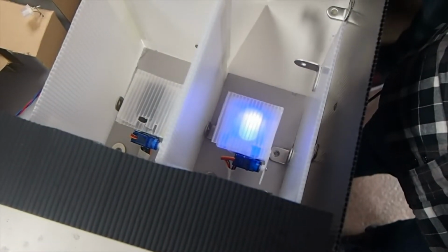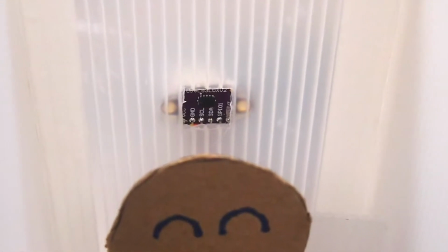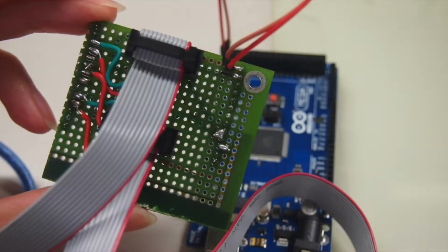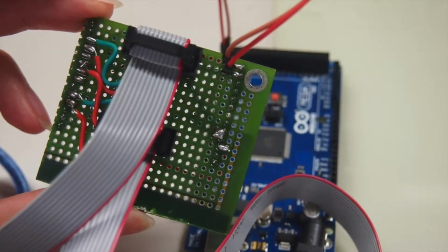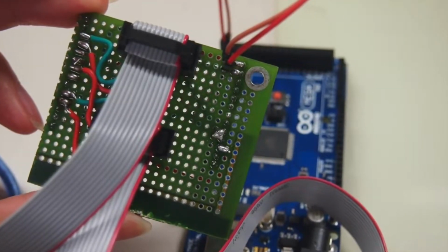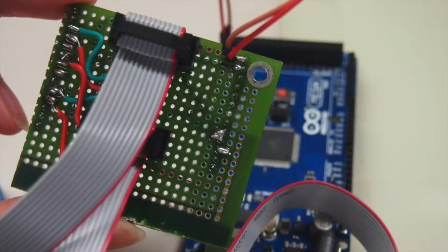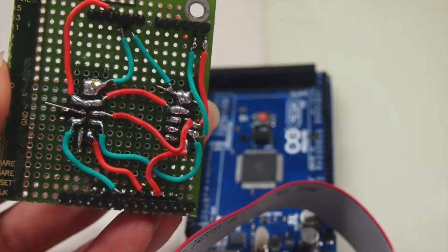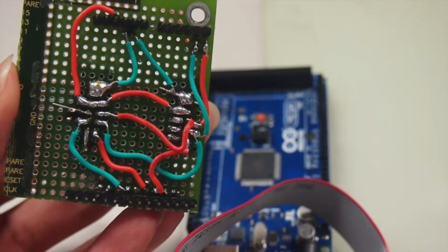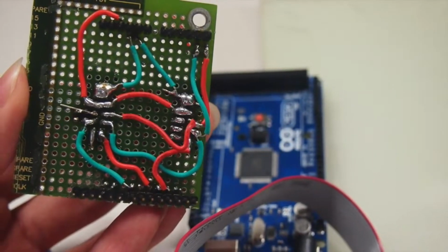The Arduino Mega is connected to VL53L0X distance sensors, a servo motor, a UV LED and a buzzer. VL53L0X measures the distance in front of the toilet seat and sends data back to the Arduino by I2C, so that the Arduino can determine the vacancy of toilet stalls. The servo motor controls the position of the toilet lid. The UV LED is used to sterilize the toilet seat. A buzzer is used to mimic the flushing sound of the toilet.